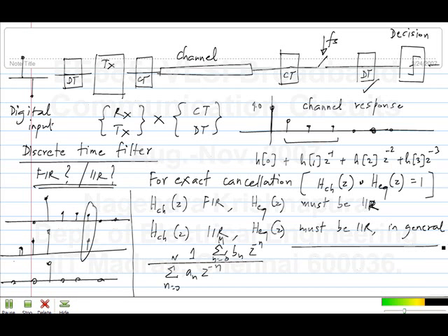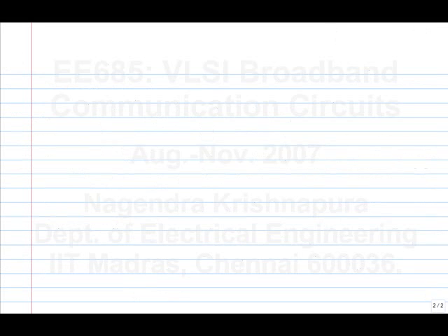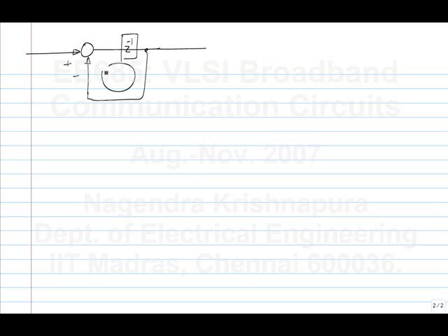So there is a problem with stability that is not just in this kind of impulse response level itself. When you talk about complicated digital filters, there is quantization of coefficients, and that's why it can move out of the unit circle and so on. But for us, we are particularly looking at very high speed implementations. So you don't have feedback in an FIR realization, but you do have feedback in an IIR realization. So for instance, you make a first order IIR using a structure like this. So this by definition implies that a delay around this loop is equal to the sampling period Ts. So if you have excess delays in the loop, you can get instability.